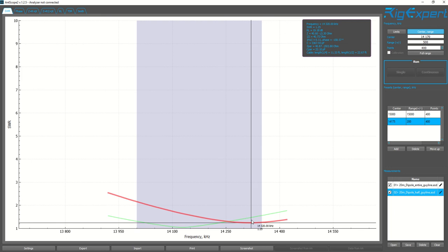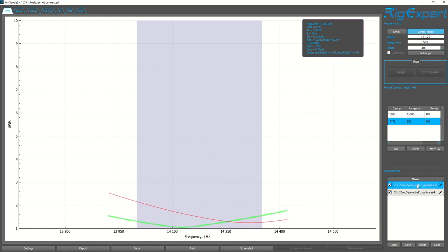So what does that mean, right? As a ham, if I want to do digital modes or CW modes, the further my radiating elements are off the ground, or the larger the angle is at the top of my dipole, the lower the resonance is going to be. So if I want to work FT8 or CW, then I want to get those radiating elements up into the air, and one way I can do that is using more guy line. By comparison, if I want to do strictly sideband, then I might use half as much guy line, and that's going to put me more resonant on the top end of 20 meters.